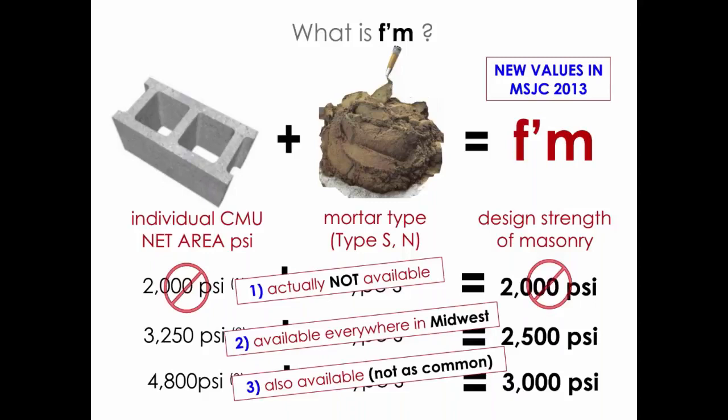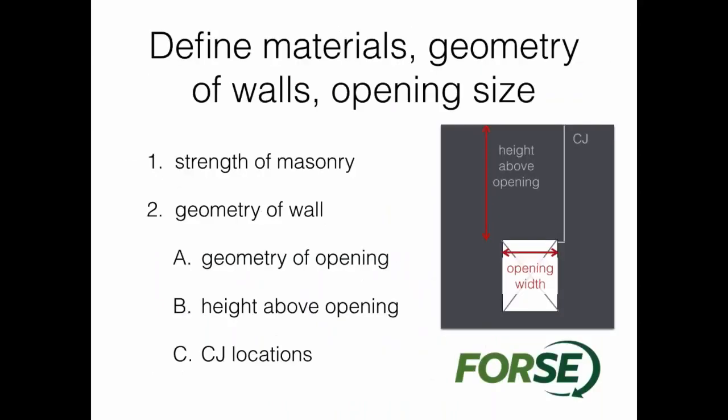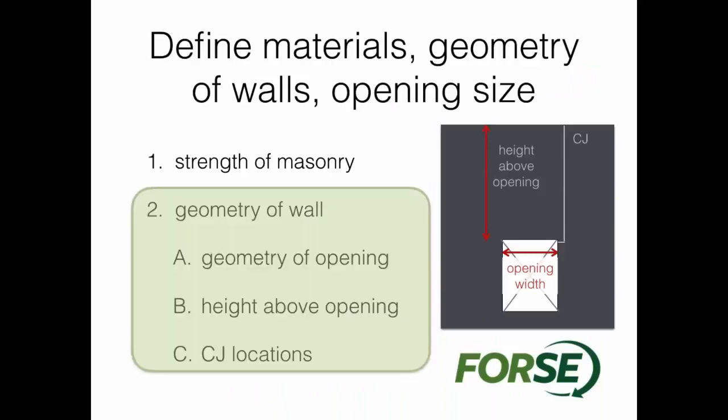That's a lot lower than that 4294 that I just showed you guys, right? Just a couple slides ago I said, remember that number? That's a lot lower. 3250 is what we need for block strength to design to 2500 PSI. I'm not talking about stretching very far here, you guys. Makes a big difference. All right, so we know what the strength is. We know we're going to use a higher strength for masonry design all over the place, and we're going to know that when we get into lintel design, we're going to be more confident that we're going to be using higher strength elements.